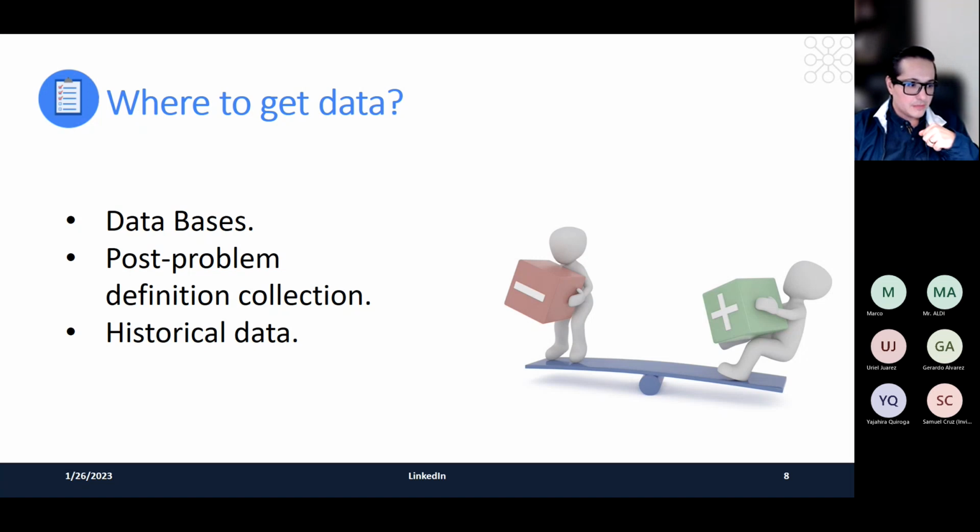Well, first of all, the pro is the information is really, really clean. Since you're not only analyzing a process, you are also setting up the standard procedure to collect that information, and you control it. The con is that it's very expensive for you, because it's going to take your time and time away from the machine or on the machine to collect that data.